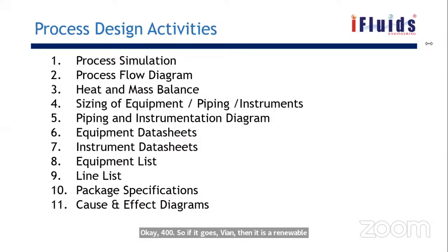The reaction is no longer with us. The temperature will shoot, reaching 400, 600, beyond the instrument range. We don't know what the temperature is then. So in that case, what do I need to do? You can put it in the chat box. Temperature control, cooling water, okay. So I need to control the inlet temperature, right? I will have a furnace in the inlet for increasing the temperature.